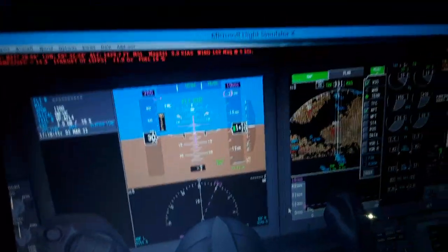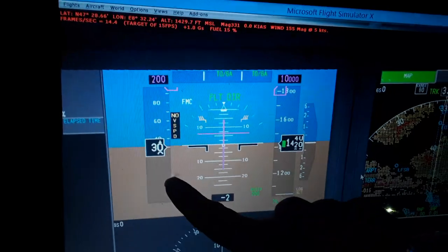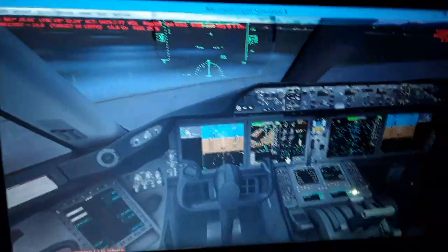So you have the airspeed indicator, and you also have a warning when you approach the stall speed over here with a red and yellow indication. So you need to have an airspeed above the stall speed. So it will give you also the flaps for takeoff 15 degrees. The horizontal trim stabilizer 4.25 degrees going to be calculated also automatically using the mean aerodynamic chord position.